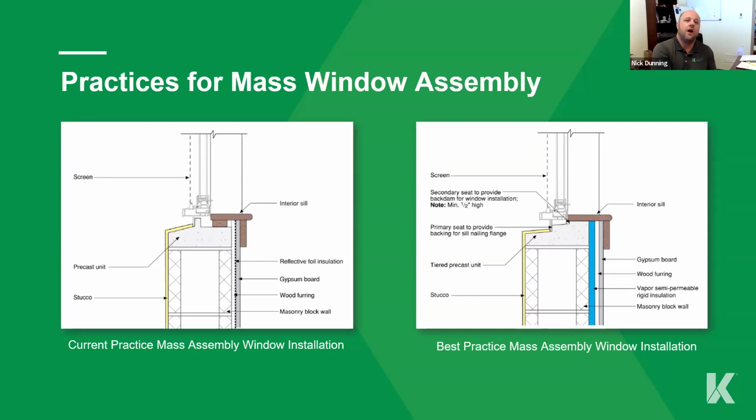Things that trap moisture, but also people working on their decks. They end up cutting it a lot of the time because they're cutting something for interior work they're doing, and there you go. You have a void in this membrane. So generally, it's going to be about a 5 to 10 year cycle. You can really get to 10 if you maintain it, and you're really maintaining that top coat, because the top coat is protecting your urethane from the UV. And that's what makes it deteriorate the fastest.